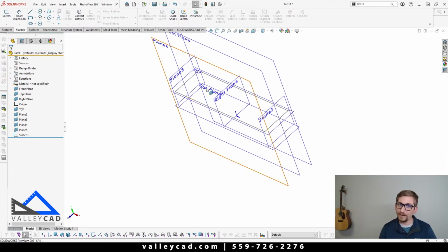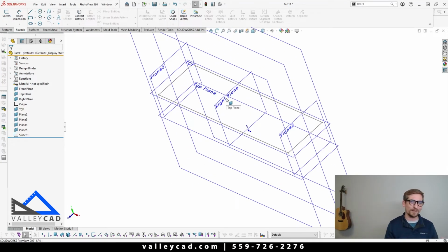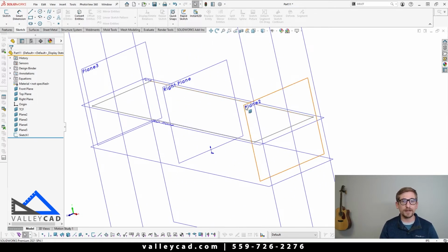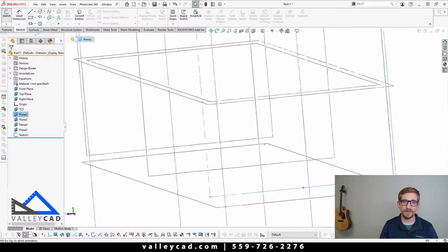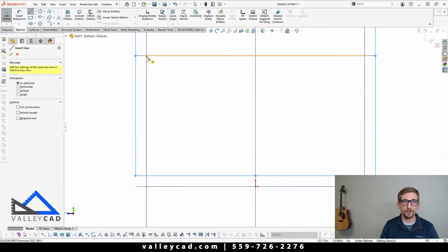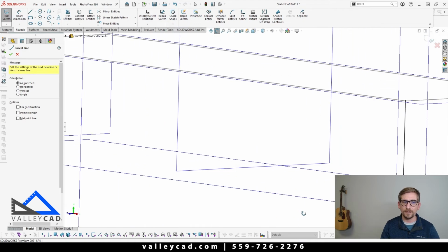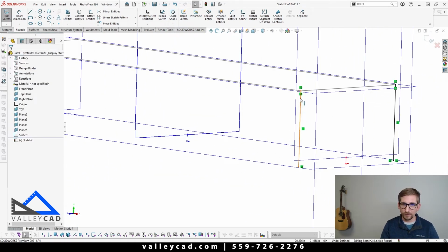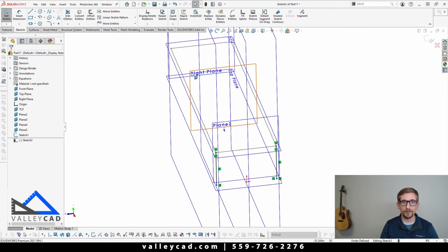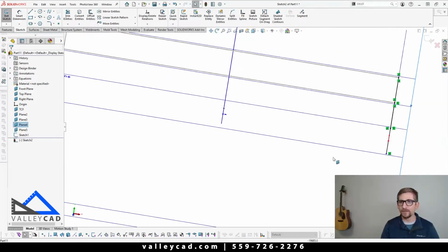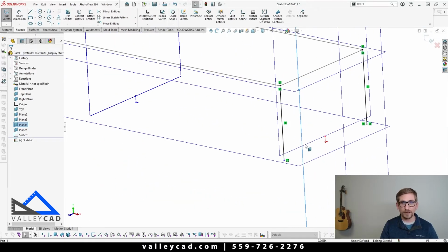And you'll see that SOLIDWORKS made all the planes big, right? That way it matches up with what sort of sketch geometry we have here. Then I'm going to come in and activate plane number 2 here and create another sketch. With this, I could draw some simple lines coming down, and maybe I want these lines to come down and intersect at the top plane here. Because it's vertical, it's going to be in line with the front of my conveyor and also on the back side. And since I sketched it on plane number 2, it will also update if I change that value at all.